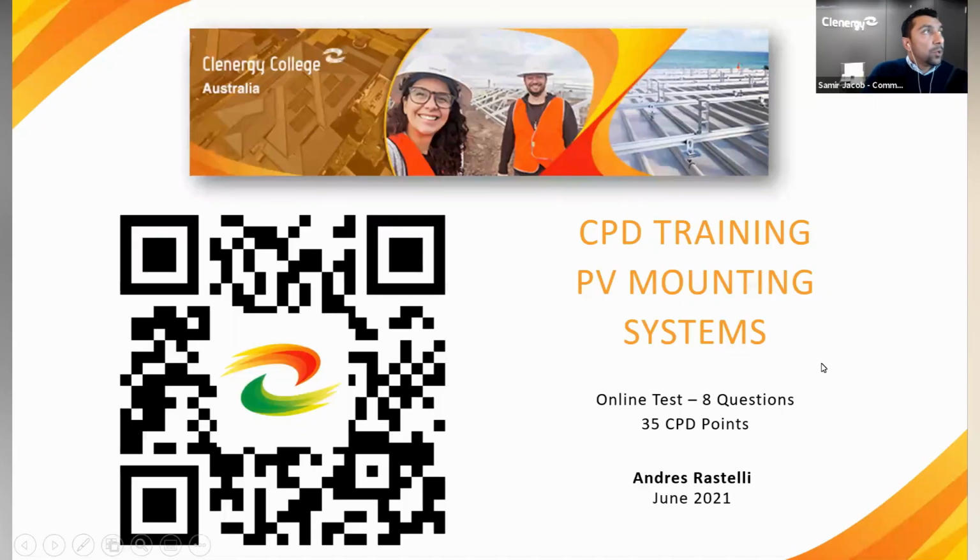Actually, we've got a couple more questions come in. So Alan, the Solar Terrace 2A frame is a steel frame. So if we secure the panels with the grounding clips on the top, then we will have successfully grounded the whole structure. And the C-post is steel, so it assures continuity to the ground. So it's not needed to have an alternative path to the grounding.